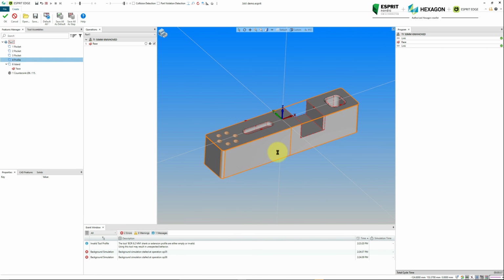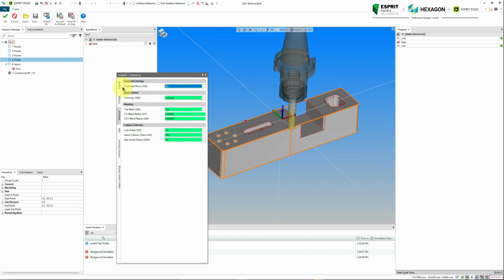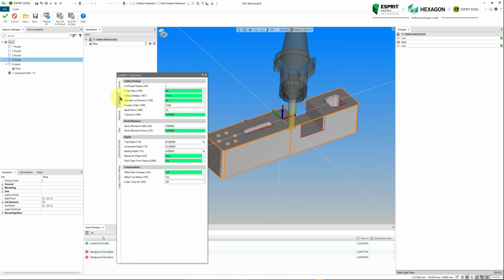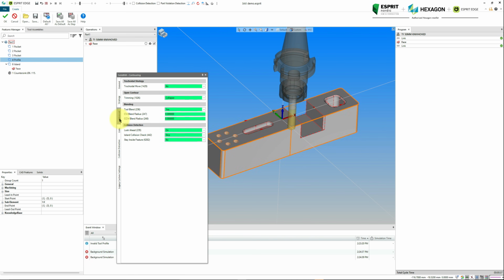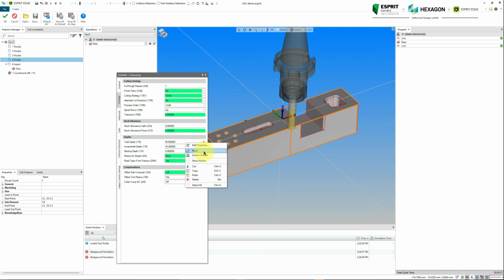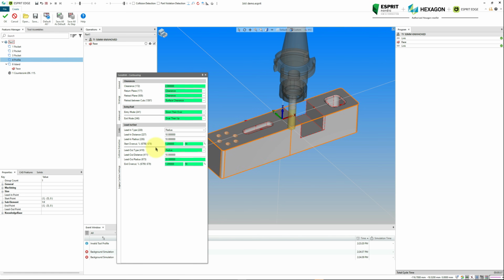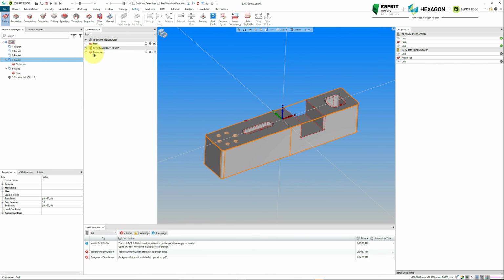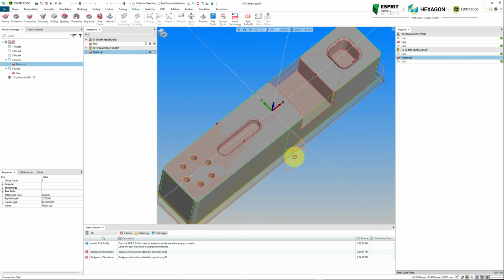Here I'm creating just a basic contouring path with a 12mm end mill. And again I'm going through the parameters just to check that everything is correct to my liking. When right-clicking in an expression field, there is the option to set System Default. If done in the Total Depth field, ESPRIT will input the depth of the selected feature. Note that ESPRIT will save the things you put into the parameters for that specific operation. This can save some time the next time you open up a contouring or facing operation.